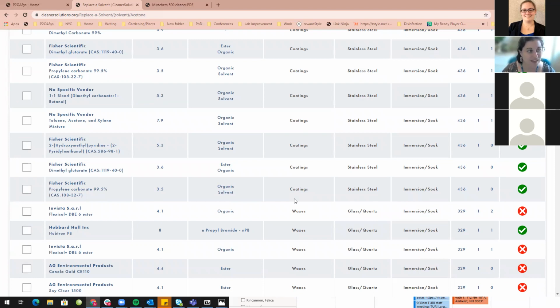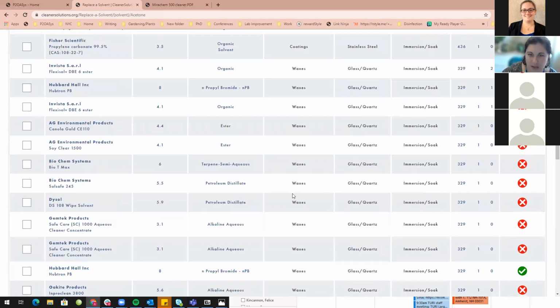That's where the company example I gave you for the metal finisher comes in. On small scale using Degrease 500 Low, they were not getting the white powder of their buffing compound on there. But when they started doing larger scale, they started seeing that. So that's what we're working with right now: finding either a rinse step or a heated dry step to remove it, because both of those options work. It's just what is more economically feasible for them. So I hope that helps.